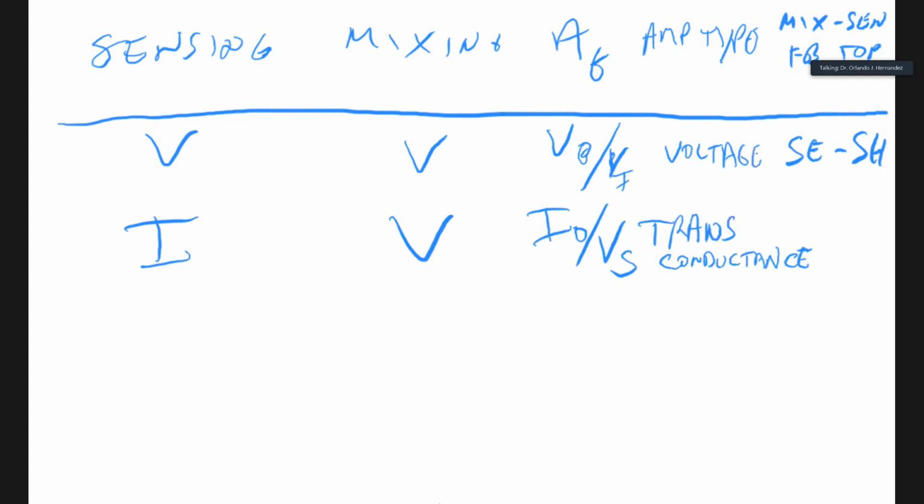So in that case, the mixing, since we're still mixing voltage, that's still series. But then, since we're sampling current, the sampling is series as well. So that would be a series feedback topology.